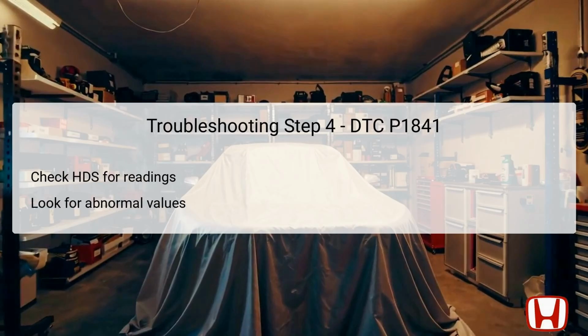The fourth step requires checking the Honda Diagnostic System (HDS) readings for the direction of secondary shaft rotation. After running the vehicle in reverse, the displayed values should confirm whether the direction is marked as reverse. If any other value is shown, then the failure can be considered duplicated.